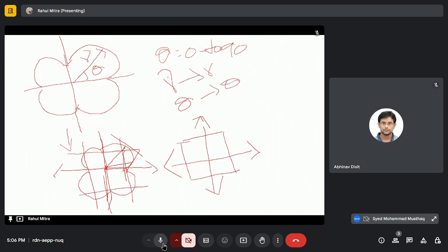So from drawing the surface free energy in polar coordinates with respect to theta, and after drawing the tangents where we find the surface free energy is minimum, and drawing a particular surface there, we have the formation of the equilibrium shape of the body. And for 111 we have something more complex. If we have a cross section, then for 111 we have a hexagon.